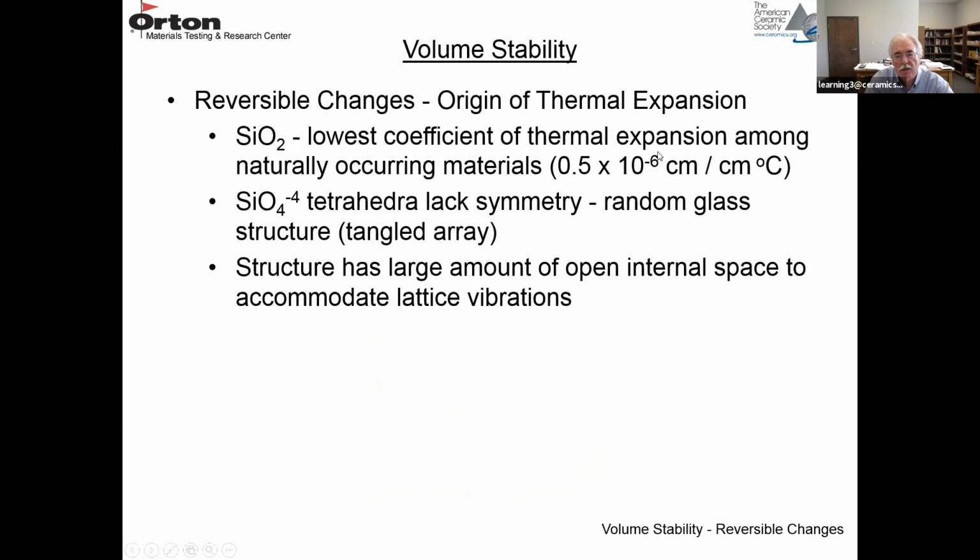And I mentioned that fused silica has the lowest coefficient of expansion among these different refractory materials, 0.5 times 10 to the minus 6. The structure of amorphous silica is based on SiO4 tetrahedra. The structure lacks symmetry.